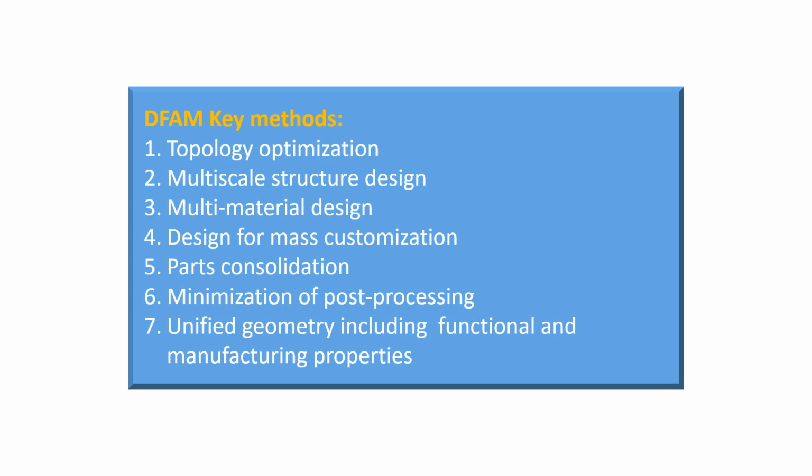1. Topology optimization. Topology optimization is the optimization of a part geometry made using the optimization feature of FEM software. Compared to other typical structure optimization techniques, such as size optimization or shape optimization, topology optimization can update the shape and topology of a part. Because topology optimization can help designers obtain optimal complex geometry for additive fabrication, this technique can be considered one of the DFAM methods.